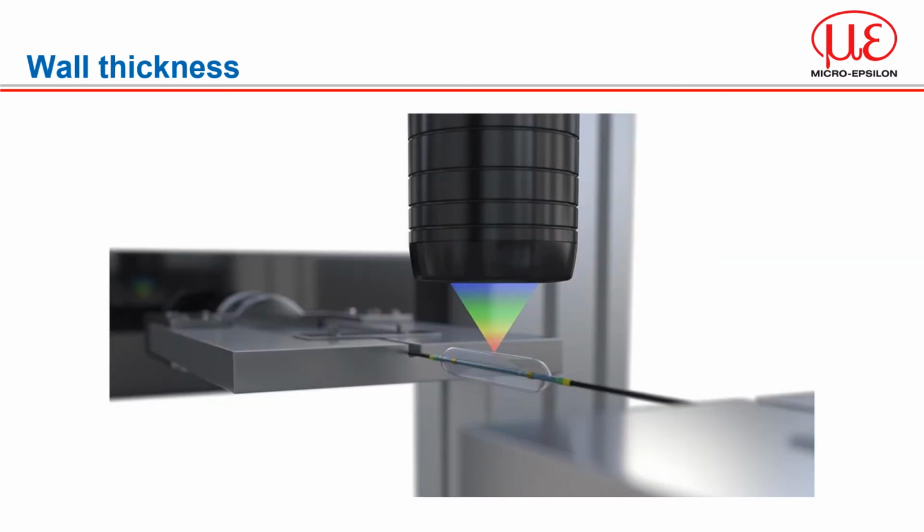In the medical and pharmaceutical engineering industry, plastic ampules are becoming increasingly important. Unlike ampules made of glass, these involve lower risks and can be produced at comparatively low cost as well as in high quantities. The production of medical and pharmaceutical products is subject to strict regulations, which are also included in different standards. Therefore, highest demands for product quality and reliability require continuous inspection of the ampules in order to ensure the patient's safety. In addition to weight and filling volume, the characteristics to be inspected also include the wall thickness of the plastic ampules, which can be achieved with one confocal sensor.